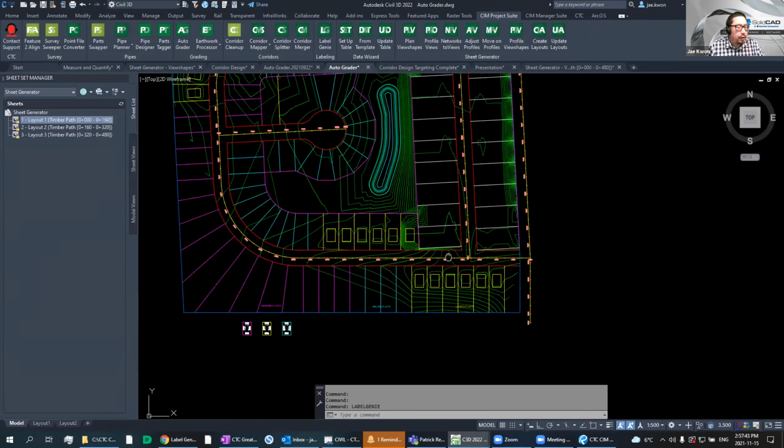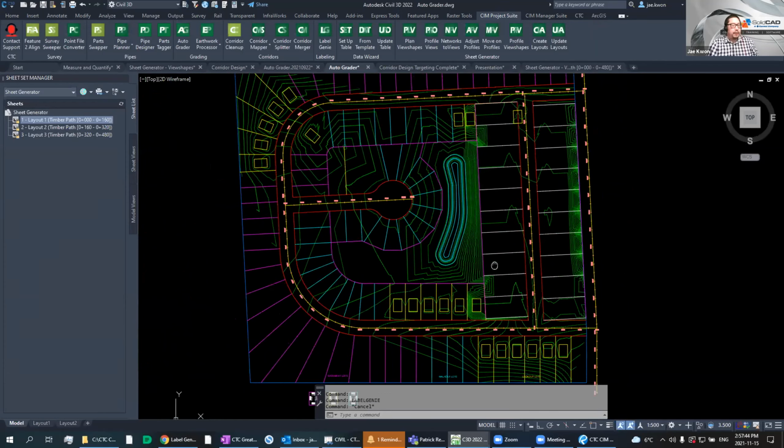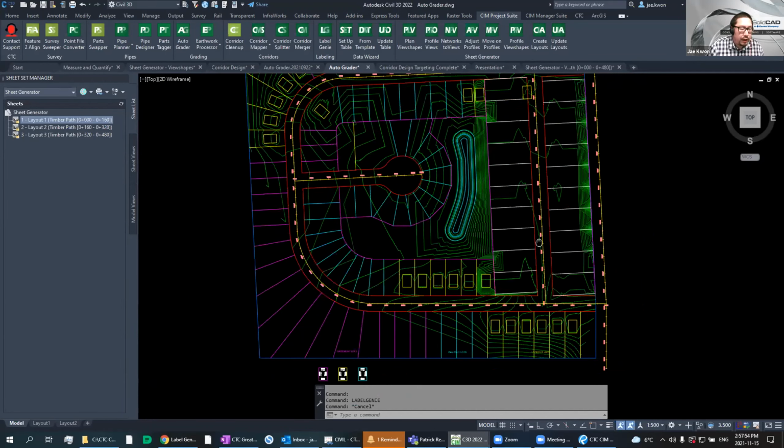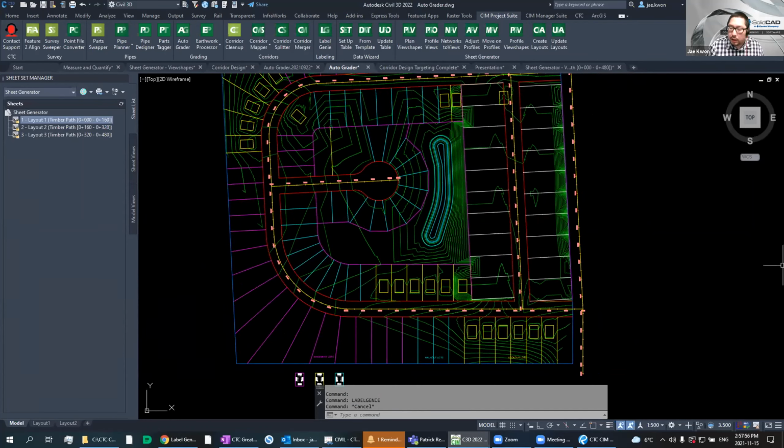So I know in an XREF, when you click on it, it just gives you the layer of the XREF itself. So you might have to do like an XLIST command, but as long as you know which layer it's sitting in, you can easily do that through the XREF. Okay. So I don't see any other questions for the moment, but I'll pass it back to Patrick to take any more questions if there are, or for the close.